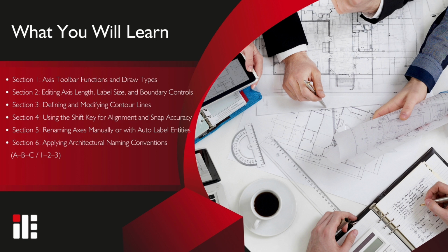You'll also learn how to offset axes manually or by using reference drawings, switch axis direction with the spacebar, and control visibility with axis boundaries and contour lines.